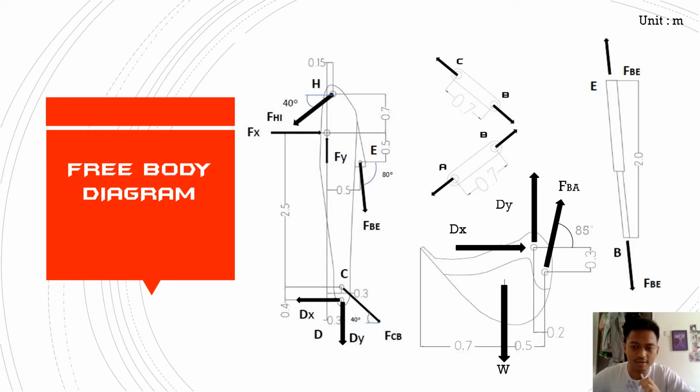Okay, now let's continue with the free body diagram. Hakim and I have discussed and come up with this final free body diagram. For example, here FHI is going to the left down, FBE to the right down, FCB to the right down. Same goes to the bucket here. As you can see, FBA is going up right, DX right, DY up, and W down.